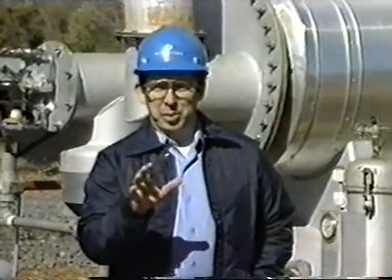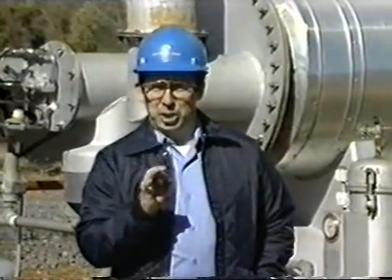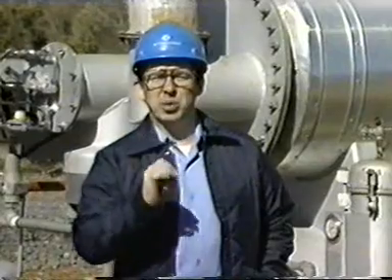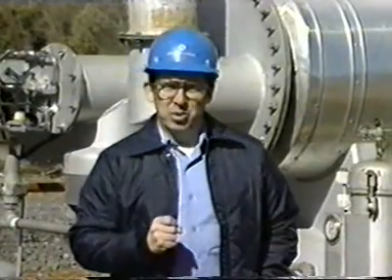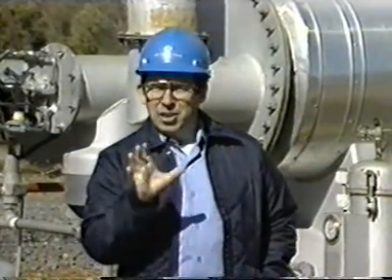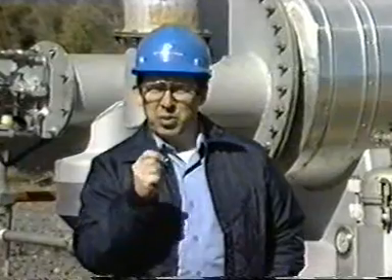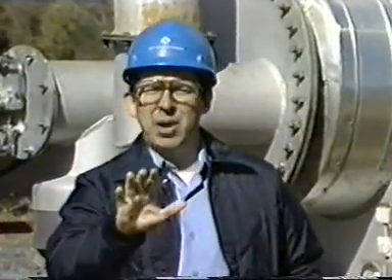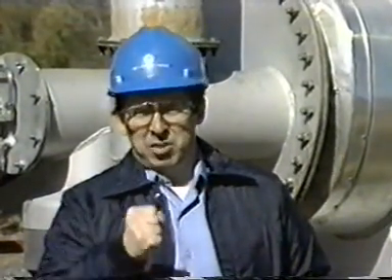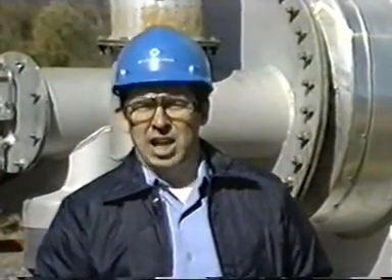The process variable with the greatest effect on dew point depression is the degree of glycol reconcentration, also known as glycol purity. Higher dew point depressions can be obtained with higher glycol concentrations. However, stripping gas must be used to achieve these levels of glycol purity.